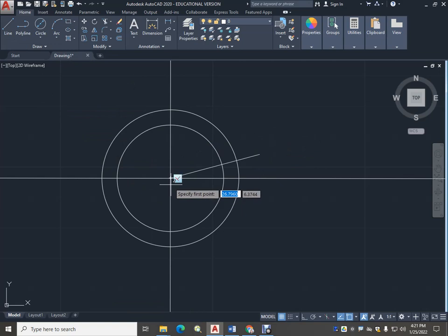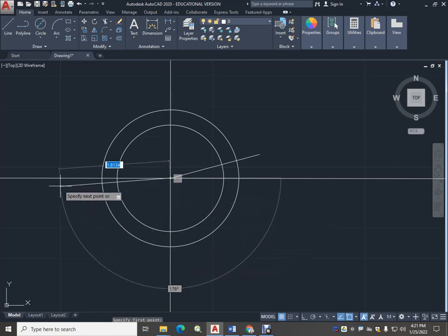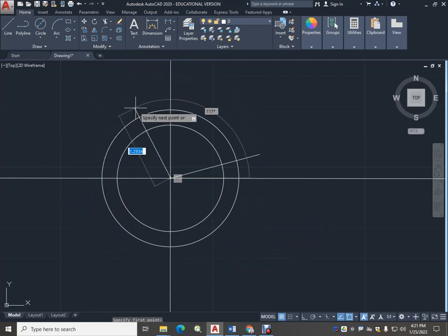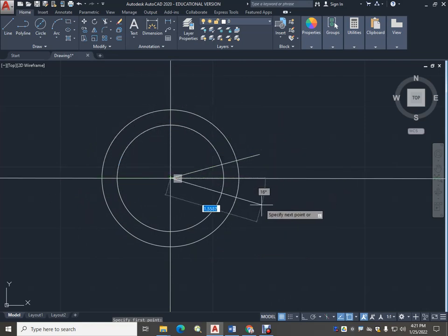Let's go in the other direction. This would be the same thing. Remember that AutoCAD always takes this line that moves to the right as 0 and then counts it out in terms of degrees. When it gets to this one, it gets to 180. And now on the opposite side, it counts down. Let's hit that tab key and do 15 degrees.